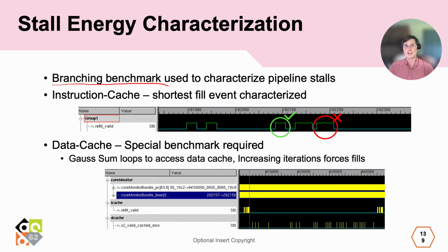And then as for the data cache fills, we had to come up with our own special benchmark there, mainly because none of the microprobe generated workloads had any data cache fills at all. So we created a special benchmark, which was a simple Gauss sum program, and we found that by increasing the length of the Gauss sum, we could force certain numbers of data cache fills. Then by subtracting the actual power from the workload using our previous instruction level power model, we were able to get a pretty good idea of how much energy was consumed by a data cache fill event.